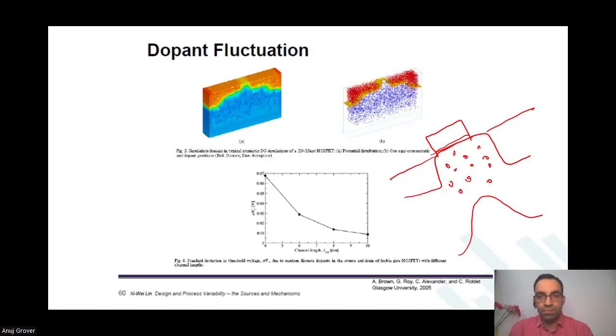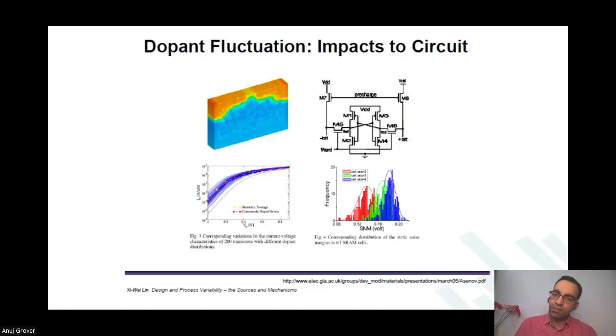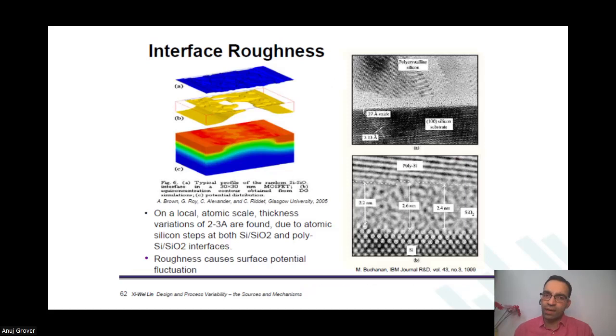Okay. And sir, like the dopant example you gave here, for worst case dopant there would also be some devices, but we will try to qualify all the devices at this same point on the curve? No. That is where we did that, no? We said this is my distribution, and we said let me put pass gate at -3 sigma, let me put pull up at +3 sigma. You remember? We did that. So we did not say that all devices are at one place. We actually, for verification, for designing, put devices at different corners, and that was when we did it.